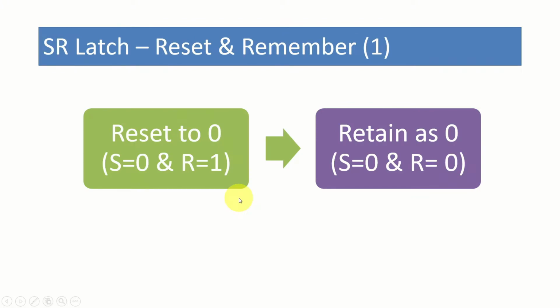Now we are going to look at how we can reset the SR latch to 0. So when we reset the SR latch, we have to provide the R equals 1, S equals 0 input combination.